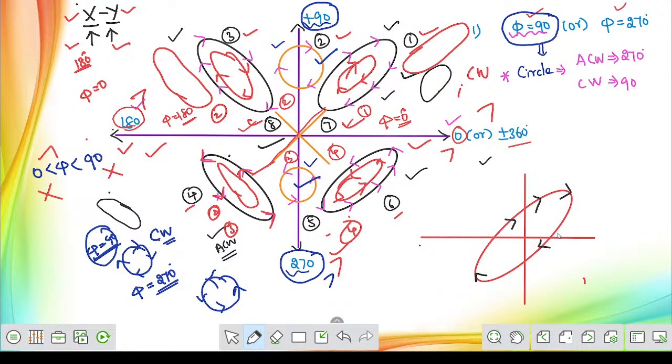Now the question is we will have to identify the exact phase angle. For that, they will give 2 points. One is the intersection point. Either they will give it on the y-axis or on the x-axis. Let us say y minimum, y maximum is given. How should I calculate the value of phase angle phi? First thing is you have to observe what type of range this type of pattern has, in which range the pattern will give you the phase angle.